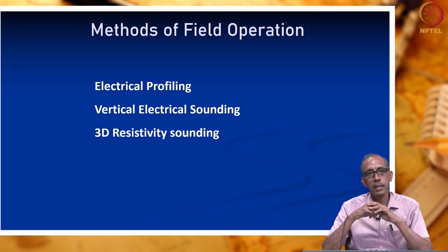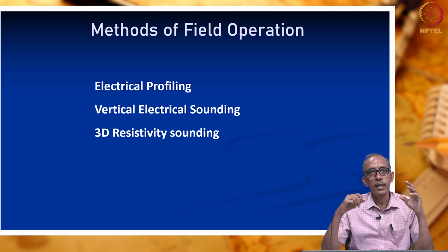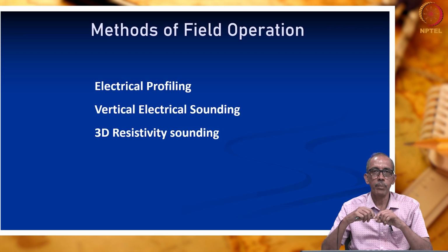So, in today's lecture, we have understood the differences between the three principal methods of electrode arrangement, which means the advantages and disadvantages of Wenner, Schlumberger and dipole-dipole method. After that, we had a look into the relation between the distance between the electrodes and depth of penetration, and also toward the end we had seen what is the area we are investigating beneath the surface.